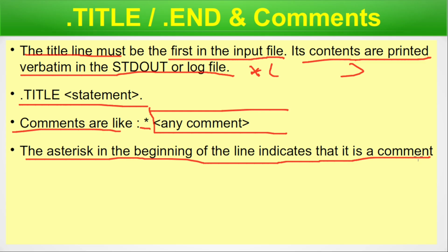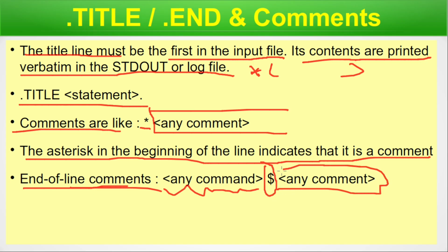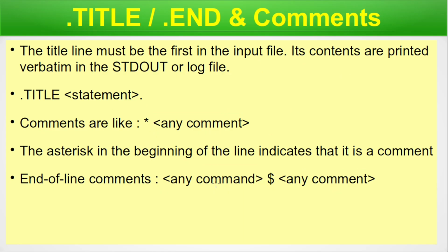That means the asterisk makes a line inactive to the simulator. End of line comment, or you can say inline comment. End of line or inline comment is like that: a couple of commands or components, and then we have a dollar, and then we have written something in words. So anything in this fashion, this part will be treated as an inline comment or end of line comment, whatever you say. Both are used terminologies in the world of VLSI.